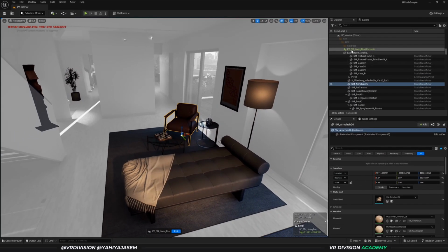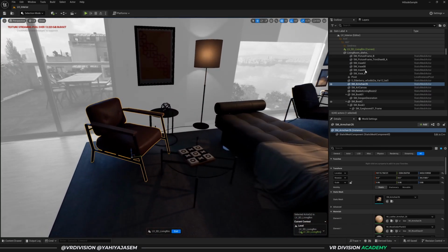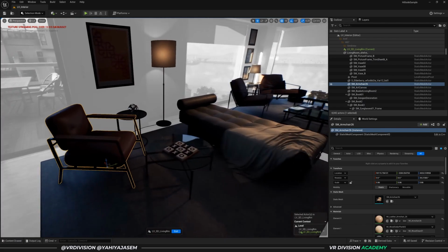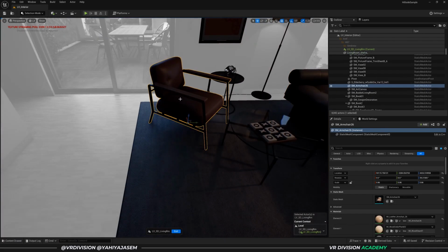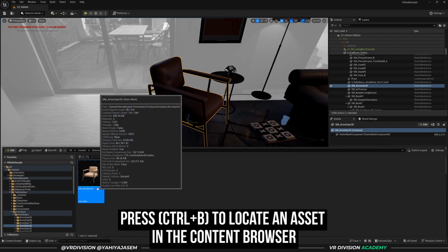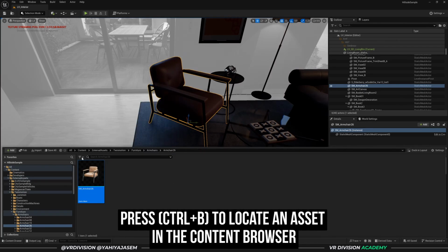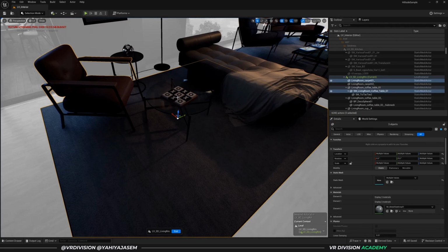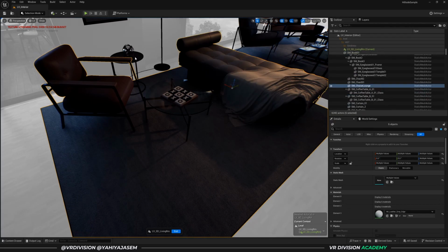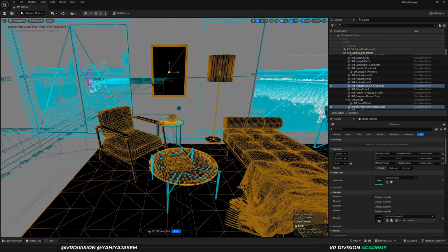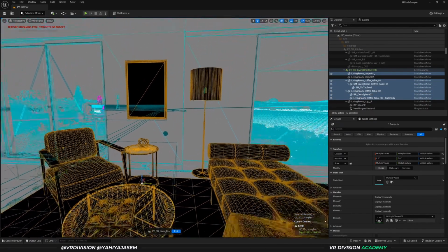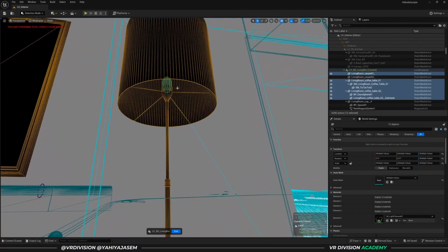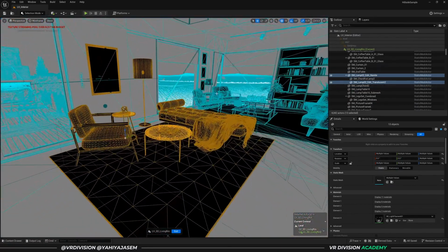And this is another way of using our levels. For now, all you need to know, when you open any of Epic items and you want to edit them and you're not able, or something's wrong, you can right click and edit. So you can select this as any normal mesh and press Ctrl B, and this is from Twinmotion assets. So let's say 1, 2, 3, 4, these items here together. I sometimes switch to wireframe or other views just to ensure I am selecting all the meshes I want to migrate. So do you have the lamp here? Yeah, now we do. So, yep, Ctrl B.